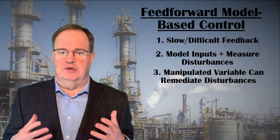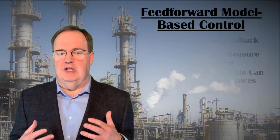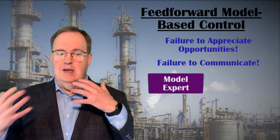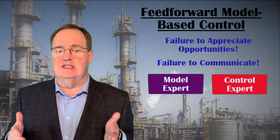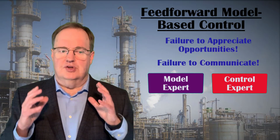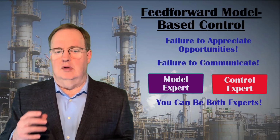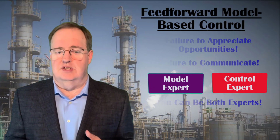The major obstacle in not using more model-based feed-forward control in process plants is a failure to appreciate the opportunities and to communicate them between the chemical engineers with the models and the control engineers who can implement the design. It takes a process engineer who understands control system design to seize these opportunities for improvement, which are most certainly out there. Model-based feed-forward control should be much more widely used in the process industries.